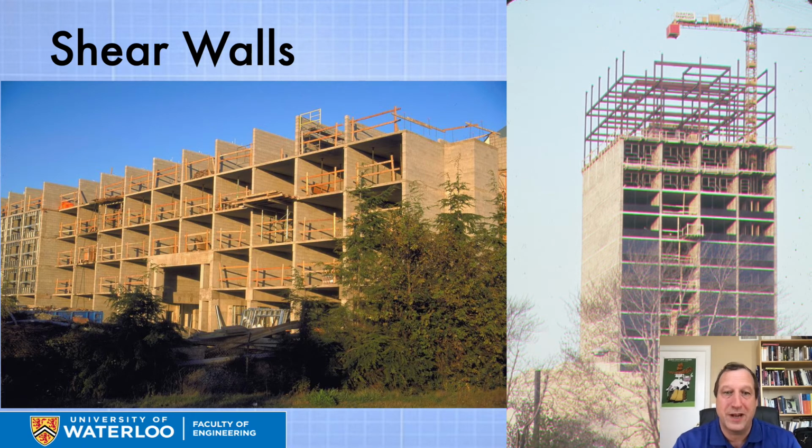This is a hotel/motel. And so having a solid concrete wall between suites provides silence and fire protection. So CMU or concrete makes sense. And the walls to the corridor, which you can't quite see here, are providing the shear in the other direction.